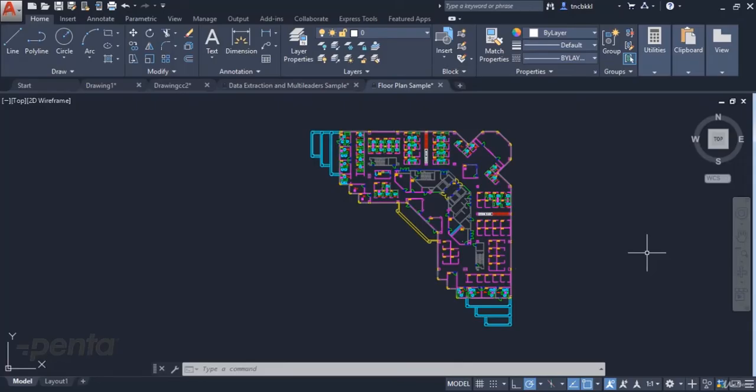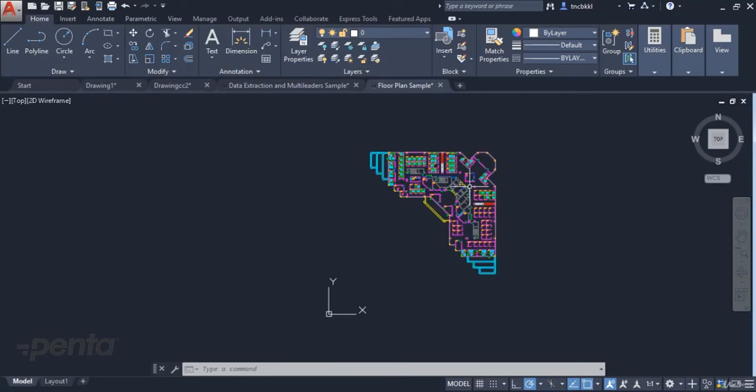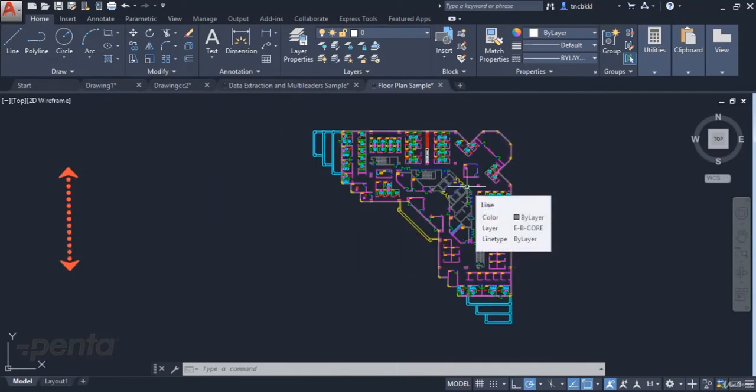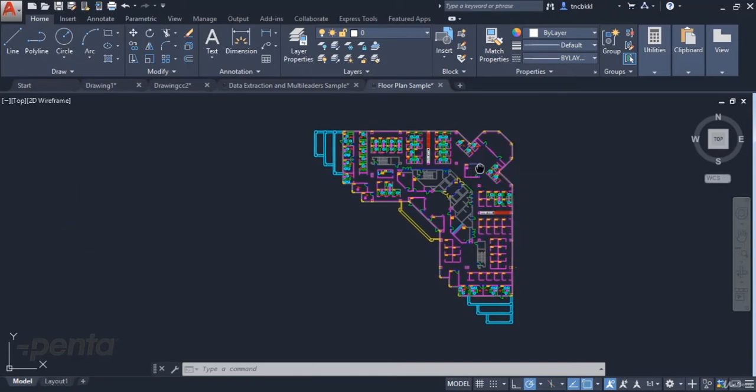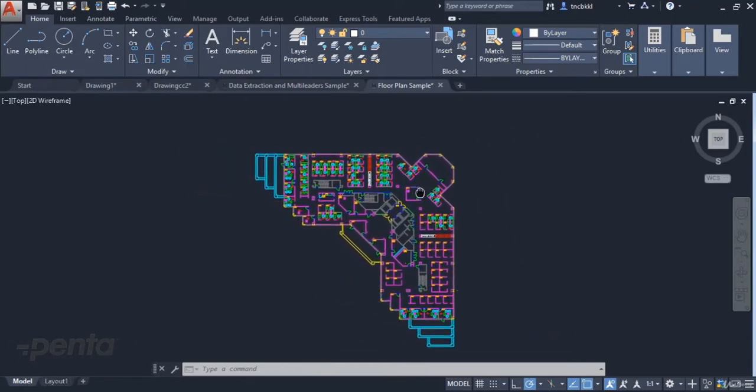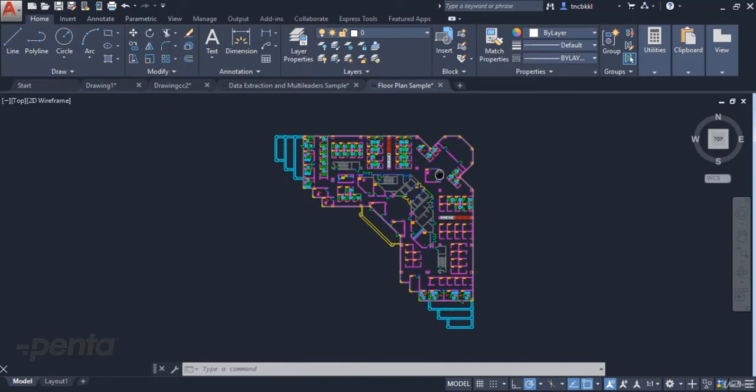In this video, I will tell you about the keyboard and mouse features in AutoCAD. We especially prefer mice that have scrolling wheels. In this mouse method that we call the 3-button mouse, we can zoom in and out of parts by scrolling up and down. For example, when we hold the wheel, the pan command, which we learned about in a previous video, is activated, and the object can be moved in a direction.